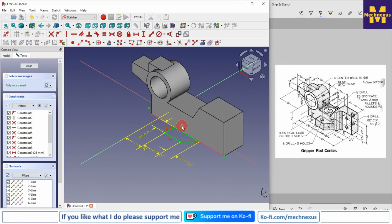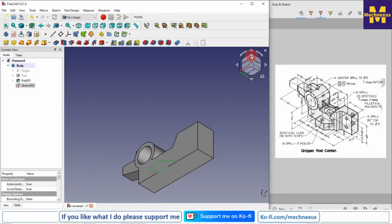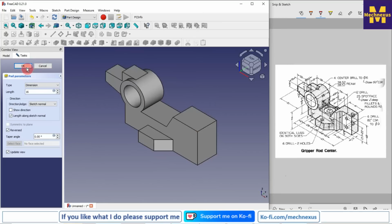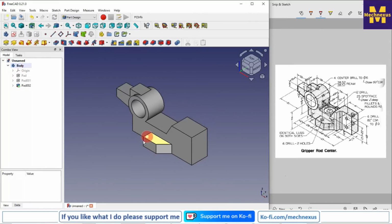Switch to the flat lines and come out of the sketch, and this extrusion length will be 16 mm. Click on the pad. So here we are not seeing anything on the screen, so simply click on reverse and give the length of 16 mm. Click on OK. Now we will move to the next feature.